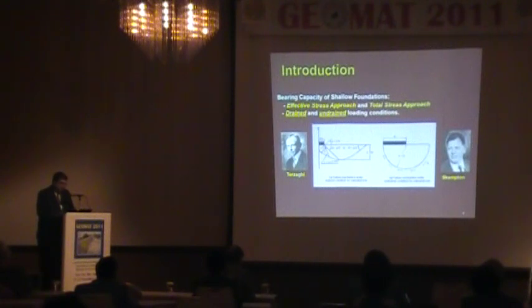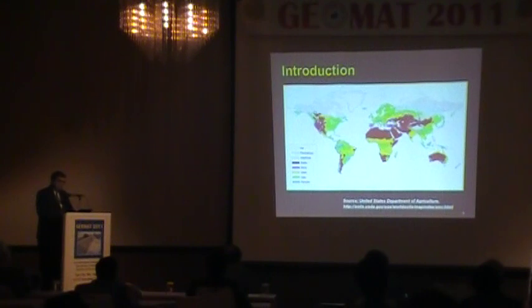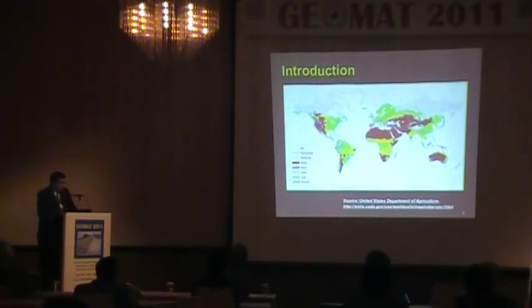Terzaghi did most of his work in Massachusetts, where you have Boston blue clay and the soils are saturated, and Skempton conducted his work mainly on London clays, where the soils are typically in a state of saturated condition. But let us take the real case scenario. If you look at this picture, we have soils which are more in a state of unsaturated condition rather than saturated condition. However, we always assume the worst case scenario that the soil is in a state of saturated condition.